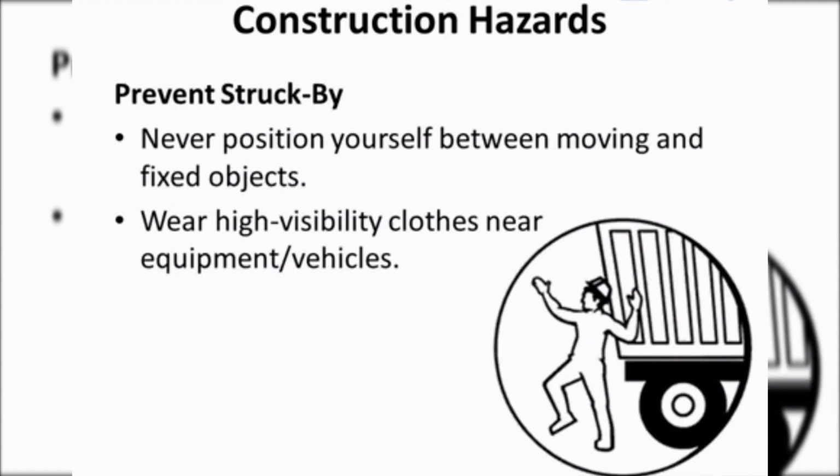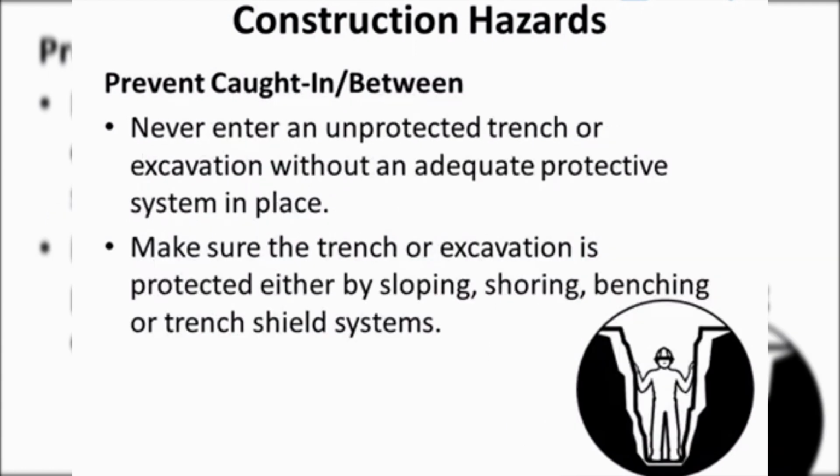Construction hazards: prevent struck by. Never position yourself between moving and fixed objects. Wear high visibility clothes near equipment and vehicles. Prevent caught in/between. Never enter an unprotected trench or excavation without an adequate protective system in place. Make sure the trench or excavation is protected either by sloping, shoring, benching or trench shield systems.